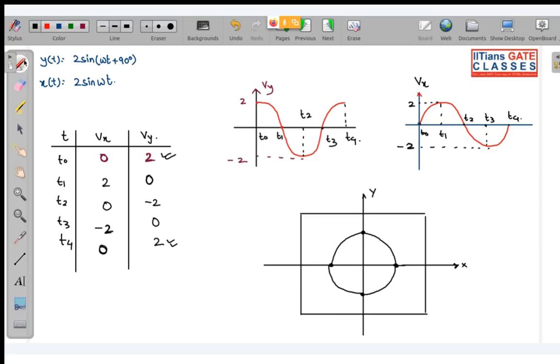So we get a circle when basically the amplitude is the same and the frequency is also the same, but the phase difference is 90 degrees. See, basically I am trying to explain that I am measuring phase over here. Why? Because I can manipulate this amplitude, it's up to me. The thing that I am measuring over here is basically the phase.